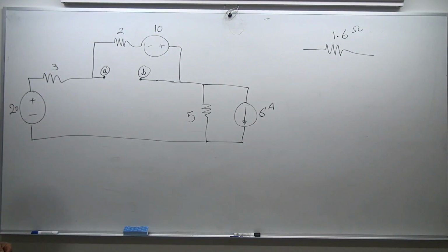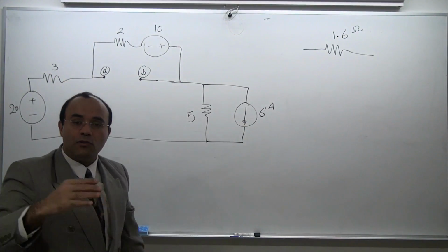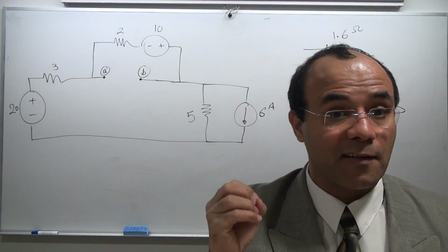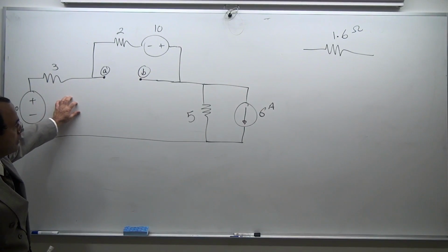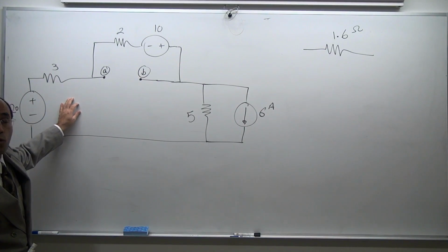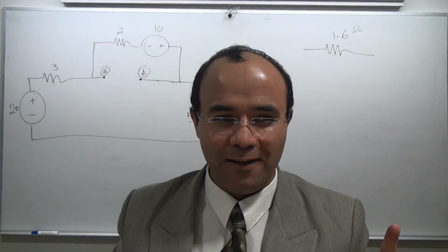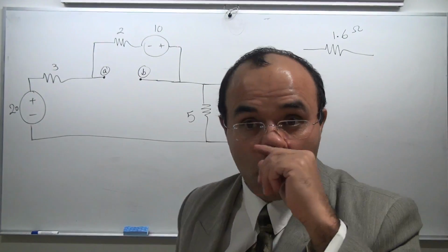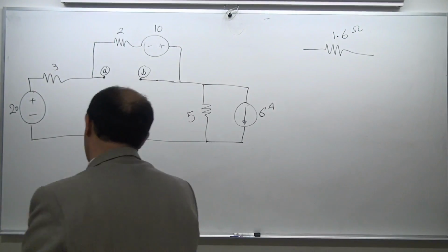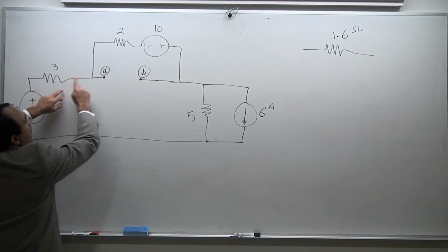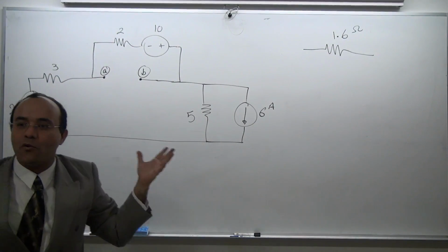Well, you have a bunch of techniques you can do. You need to find this voltage versus the ground, this voltage versus the ground, subtract that. I want you to sit back for just a couple of seconds and make the smart decision. Do you want to do nodal? Because if you do nodal, are you facing a simple nodal equation or are you facing a supernode? Of course, you can rearrange your stuff and make sure you get a simple nodal though. I challenge you to see this as a simple nodal. I want you to see it. It's really a simple nodal. But if you can't see it, give you a hint. If you switch this over, and if you switch this over, the 2 voltage sources are actually meeting here, right? If I put this as my ground, then it's a simple nodal, very simple nodal.